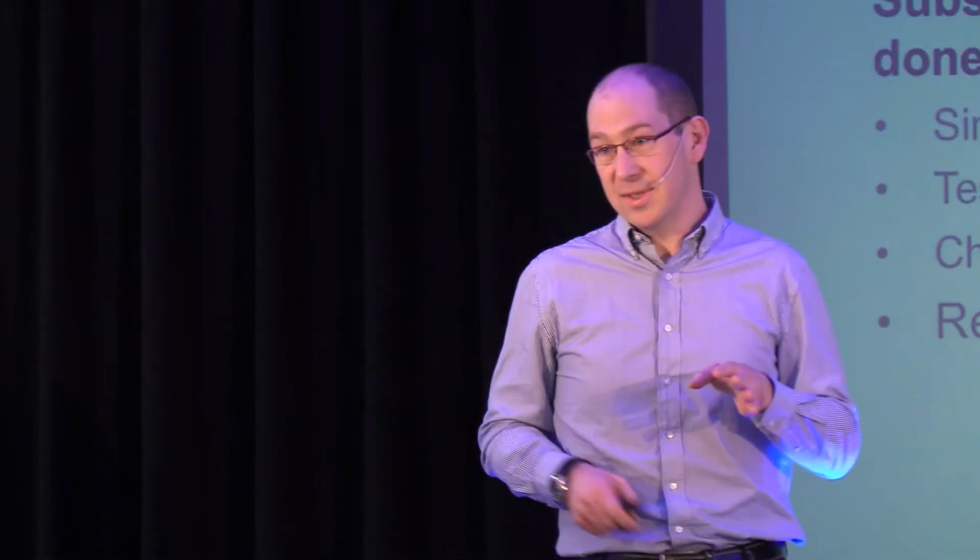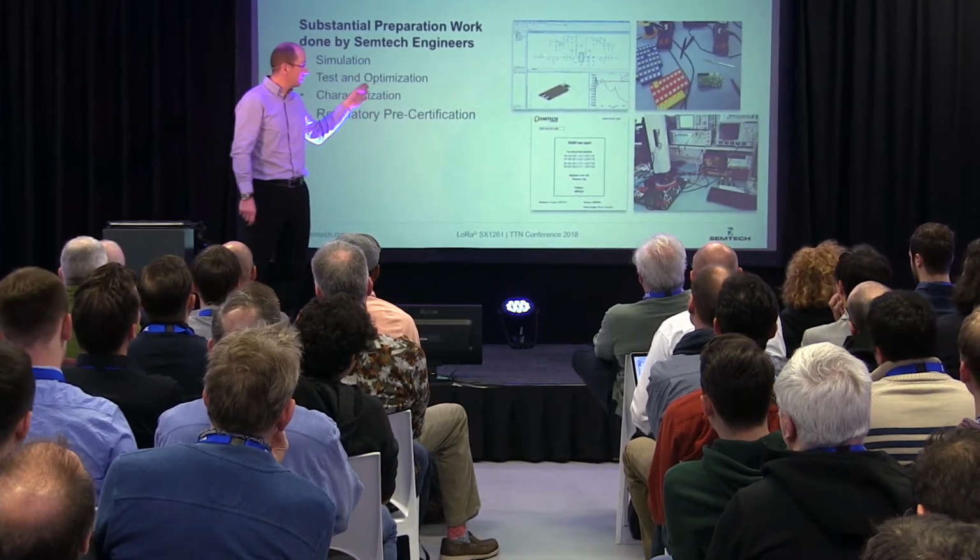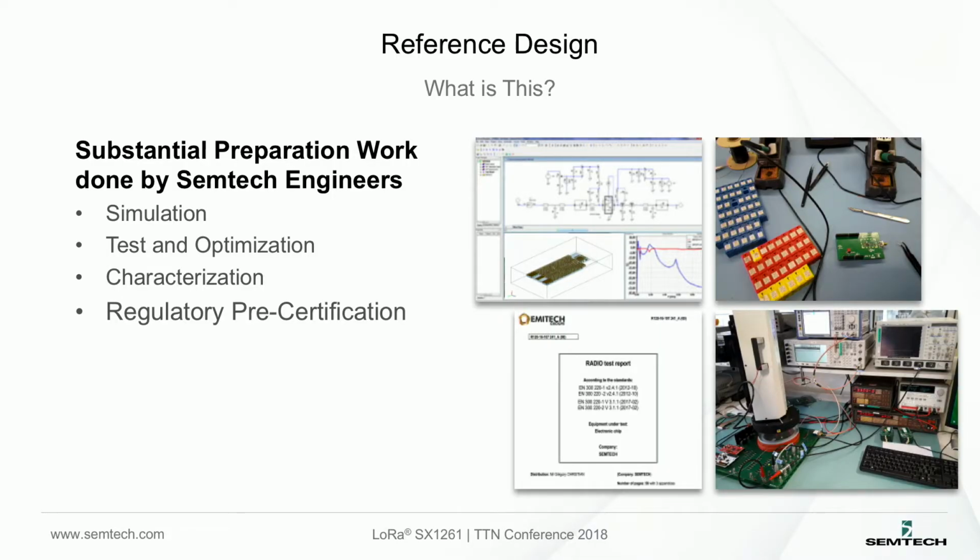There are ideas, concepts. There are tools that are being developed to make your developer's life easier. And one of these tools is the reference design. Starting from simulations, PCB simulations, I moved to tests, optimization. I'll describe the process a little bit afterwards. Then characterization over temperature, supply, and so on, to finally check that this reference design is able to pass all the RF certifications.